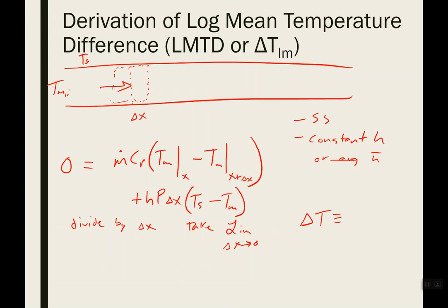Yeah, Ivan, do you have a question? What's that Tm on the thing we just said? That Tm right there, in the convection? Is that the temperature of the fluid? Yeah, that would just be the temperature of the fluid inside of here, the node. So it would be the same as this temperature actually. We're just assuming that within that node, it's a constant uniform temperature. So that's just our fluid temperature measured at that particular X.